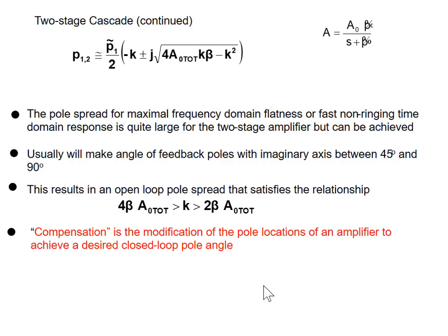Why do you think you're doing that? More power efficient. If you know you're not going to be using it at a gain of 1 and you want to save power, then why buy an op amp that's compensated for unity gain when you're not putting it in a unity gain configuration? I wonder how much this power savings could be. Quite a bit. Make sense?